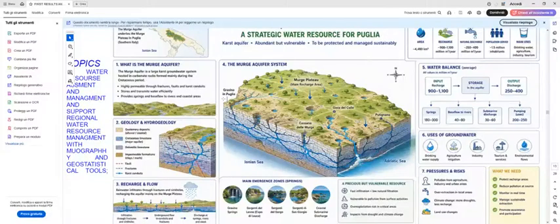You have different piezometric levels between the central part, the first part that is connected with a small width of around 3 to 5 kilometers, and the second part that is in the Alta Murge. So we have a complex system of recharge and flow: rainwater infiltrates through fractures and sinkholes, recharging the aquifer mainly through the Murge plateau.